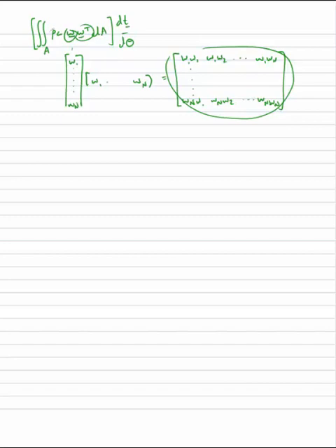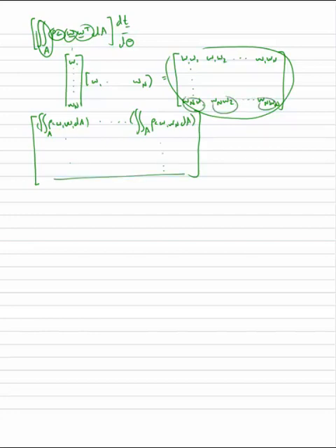If I multiply each of these by rho times c, and I integrate over the area, I'm going to get a matrix of coefficients that look like this. It's the integral over the area of rho c w1 w1 dA all the way to the integral over the area of rho c w1 wn dA. And if I go down, it's the same thing with these in the bottom, and then multiplying the whole thing by d theta of all of my temperatures, T1 through T sub n.